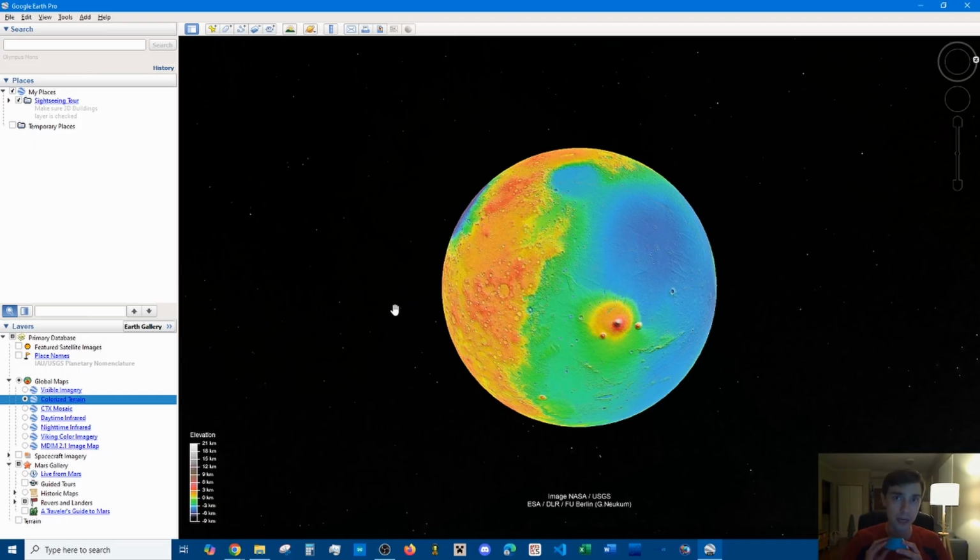We have several ways to control this during reentry. We can have it aerodynamically stable, so we have the center of gravity above the center of pressure, and we can control it from there a lot easier. Reaction wheels are totally feasible with this. In fact, I already plan on having them, full stop.